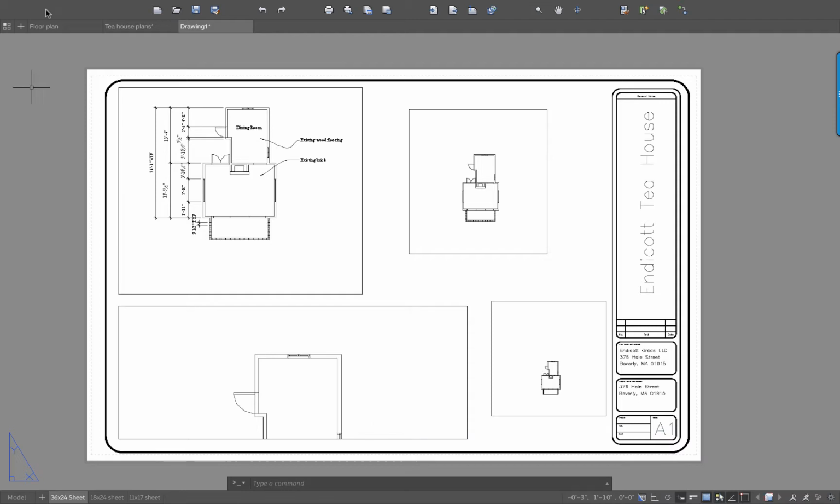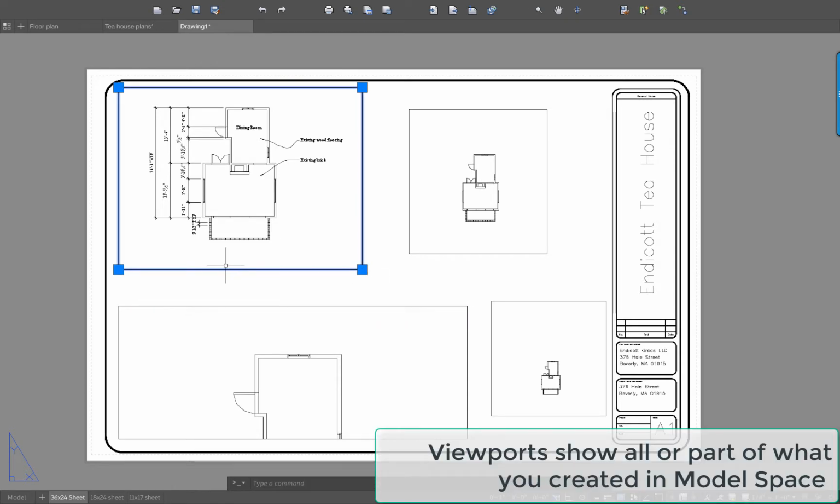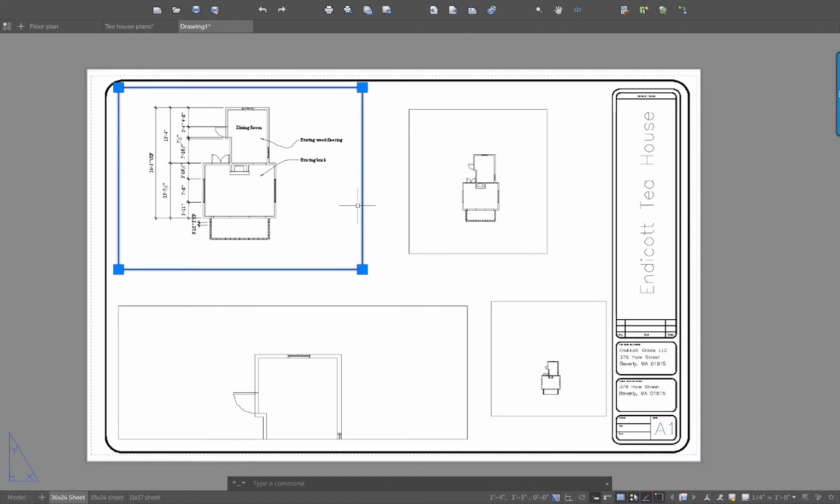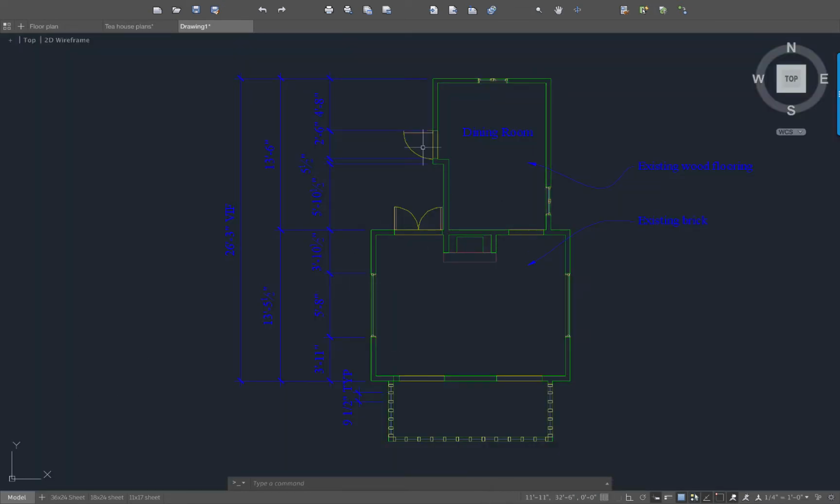Okay, so let's talk about printing our sheet of drawings here. When you print from AutoCAD using this template that has the ready-made sheet, I'm using the 24 by 36 sheet. I've set this up with a couple of different views of your model. This is the way it works. It's basically a sheet of paper, and it has these objects on the sheet of paper called viewports. These are objects that can be rectangular, they can also be other shapes, and they are views into the model space here. So here's my model.